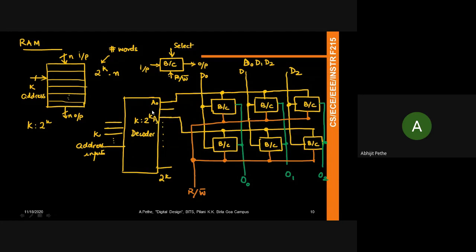So what you'll begin to see is that this decoder generally tends to be a very power hungry, slow circuit. So people have spent a lot of time on architectures, and various decoder architectures are available. When you do advanced classes, you look at that. So again, this decoder is helping you select a particular word, and each word has its inputs given from the overall input from the memory, and all the output pins are connected together, right? And this read write bar is going to tell the selected bit cell whether we're writing into it or reading off of it, right?